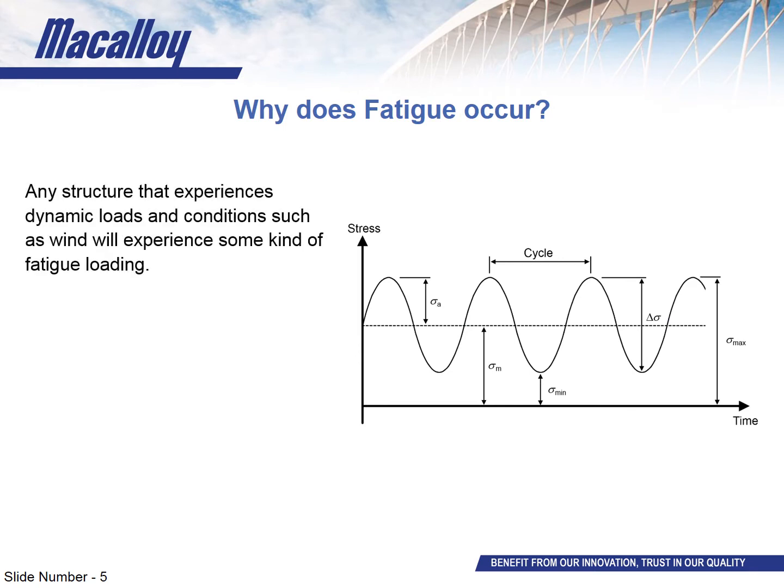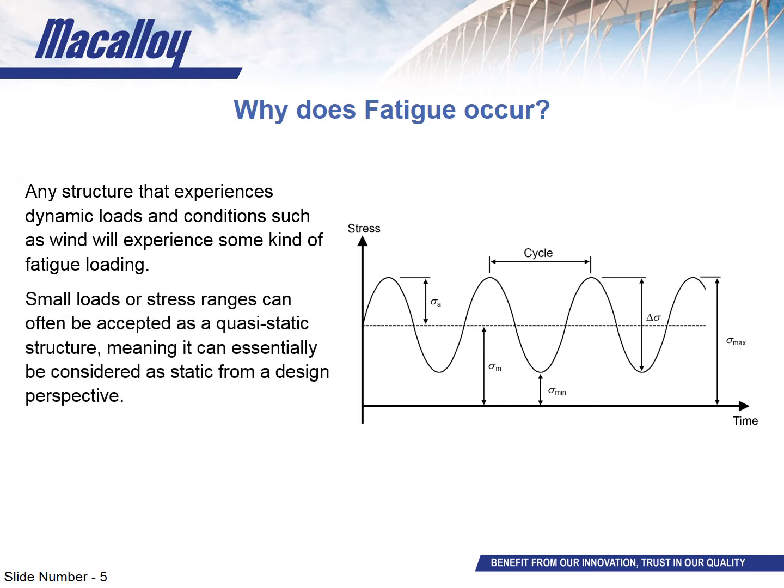If you take the description of fatigue literally, it's actually extremely common, and by taking it literally, I mean a load that oscillates in its intensity rather than being completely static. Now, a lot of structures do actually experience a small amount of fatigue as a result of loading such as wind, for example. However, if the load itself, or the change in loads, is relatively small, the loading conditions can be considered what's known as quasi-static. Now, quasi-static basically means that from a design perspective, you can consider it to be essentially static.